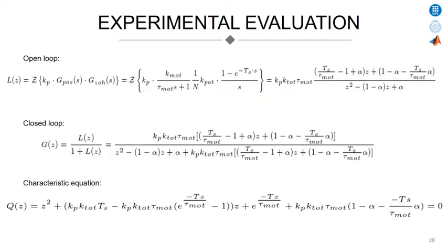In this case also, to analyze from what value the system will become unstable, as we have done previously, the plant has been digitized with the help of a zero-order holder and the closed-loop digital model has been obtained. In this case, we will evaluate the stability by applying Jury's stability criterion to the denominator.